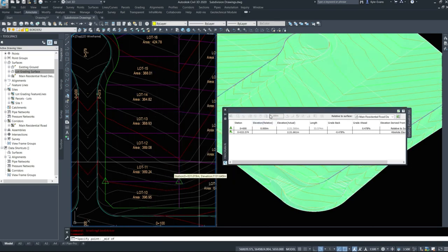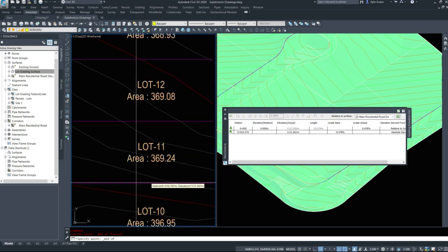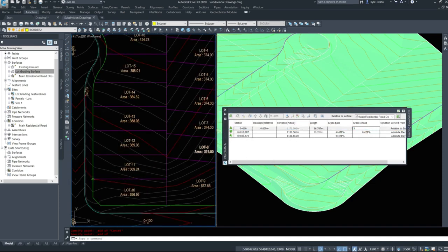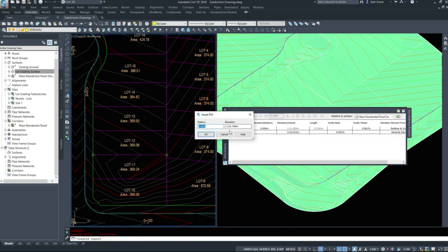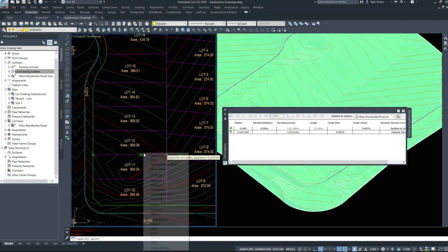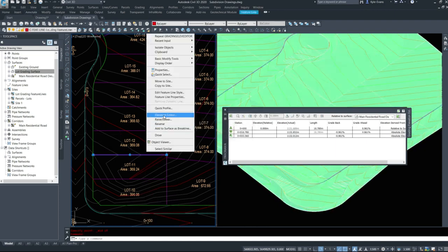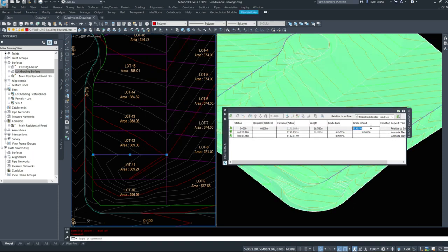That's easiest for this. So I'm going to use this button right here, insert an elevation point in the mid. I'll hit OK. And I'm going to grade the initial part of the feature line 3% up, which is -2 down. I'm going to go to the second feature line at a midpoint. We'll do elevation editor. Oh, we're already in it. And that one's 0.9 ahead. So if we go 3 up, it's 1 down. We might have to do 3.5, 4% up.